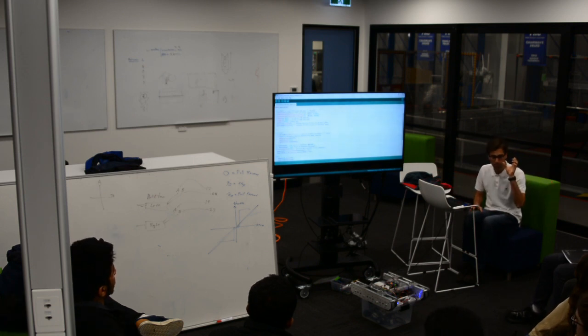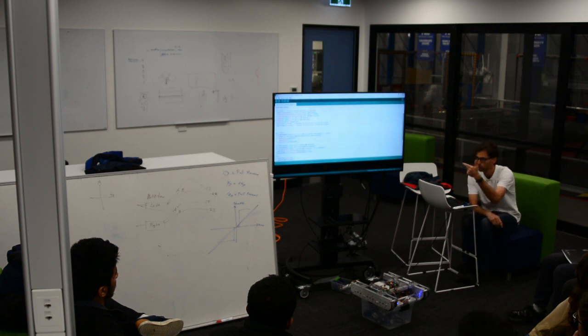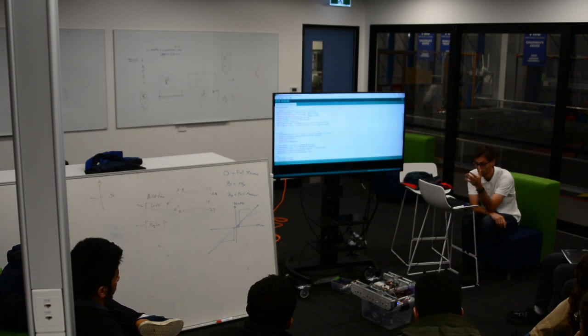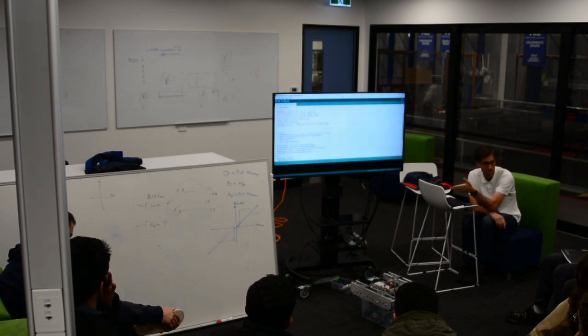So then we've got target position minus count left, we call that our error. Again, it doesn't matter if it's speed, position, or temperature, you've got to have that error number, right? And it's usually just a difference. So we're going to multiply that by 0.1. Let's just think about what it means. We typically are going to have error signals that are 500, 100, 200. So if I multiply that by 0.1, let's say it's 200, I'm at 20. That's not bad, okay? Then I'm at a throttle of 90 plus 20 or 110. That's a reasonable number, right?